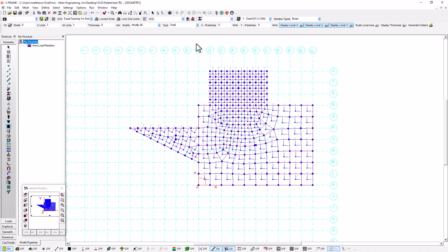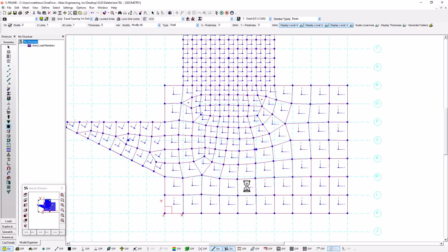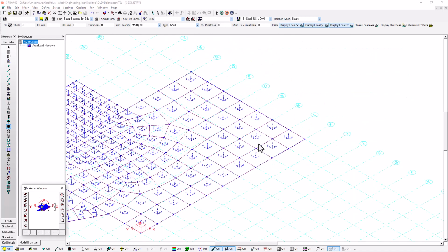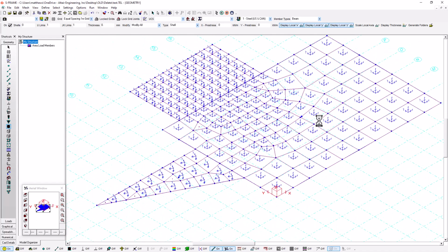And what I'm actually displaying here is with the shell element tool, the quadrilateral element tool in this case, I'm displaying the local x, y, and z coordinate systems. And we can see here, if we just zoom in, and maybe it's easier to see in 3D view actually, I can see that for each individual panel, all of these coordinate systems are aligned with the panel's coordinate system. So each shell has its own axis, and it's showing those coordinate systems.